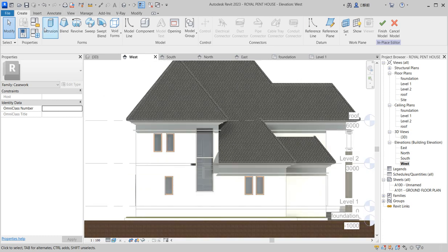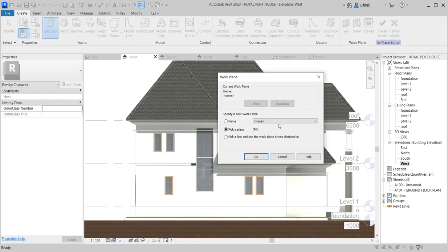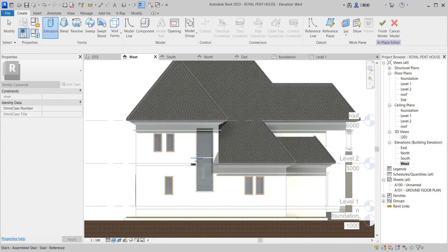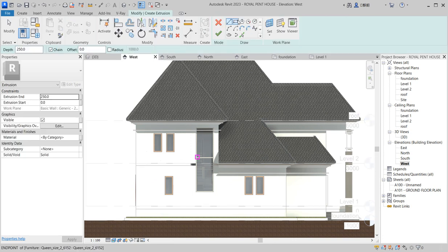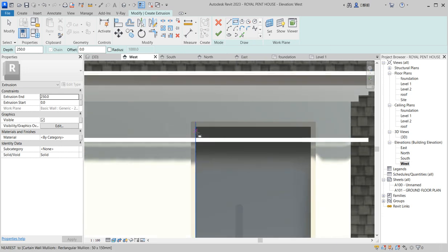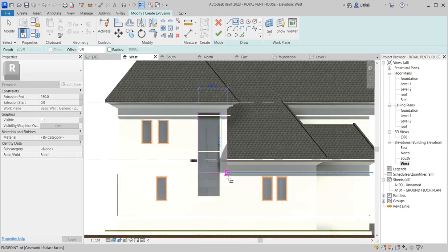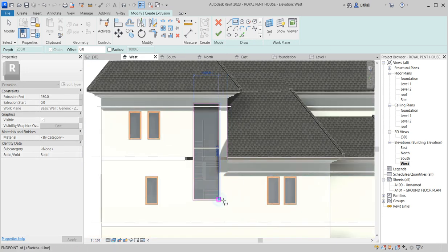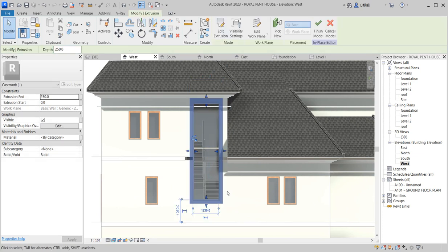But that's what I want to use. So I'm using extrusion at this junction. I'm going to use this plane level reference, which is what I want to use to create that. So what I do is I draw this line across the whole system. Next, I offset this by clicking 200. Let it be. Good. So you click finish on that.